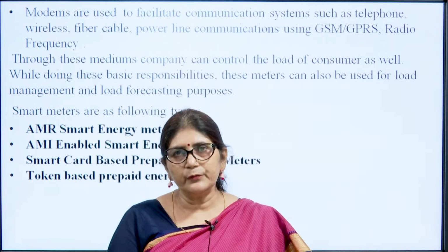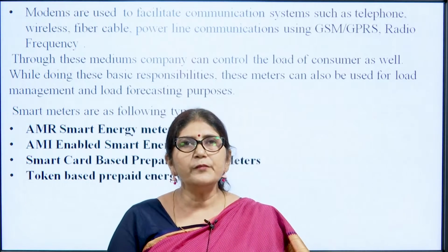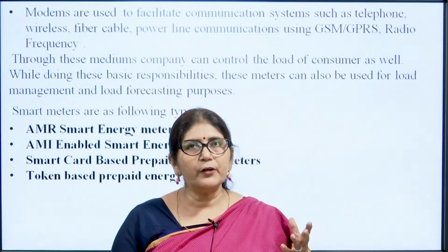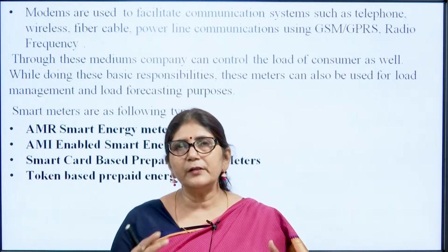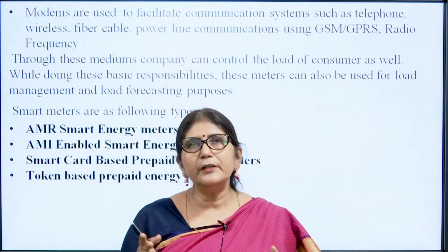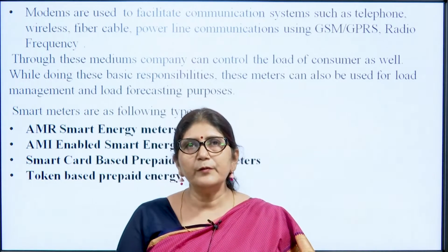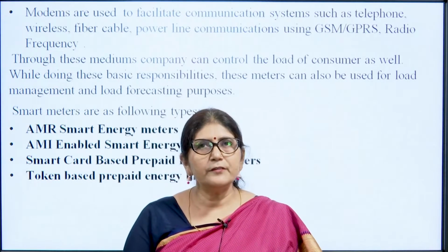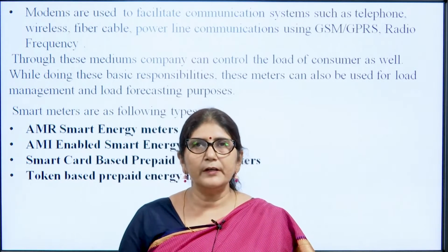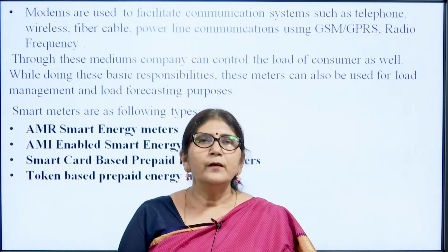Here the modems are used. Modems means modulation and demodulation devices. Modems are used here to facilitate the communication system, because we need modulation and demodulation techniques for communication with the utility office. So, these smart meters have modems to facilitate the communication system, such as communication through fiber wires or through power line, using GSM, GPRS and radio frequency.